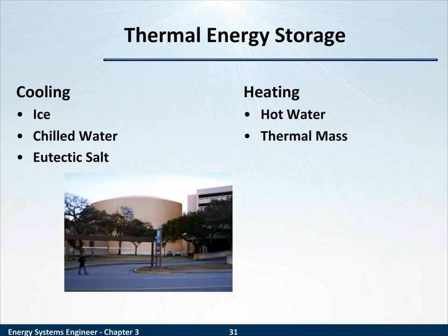Whereas the consumption of energy, kilowatt hours, as we discussed in our first chapter and in lighting, kilowatt hours of consumption is more like your odometer. How far have you come this month in your energy consumption? Your demand, however, is more like your speedometer. What's the fastest you've gone this month? What is the instantaneous maximum kilowatts this month?